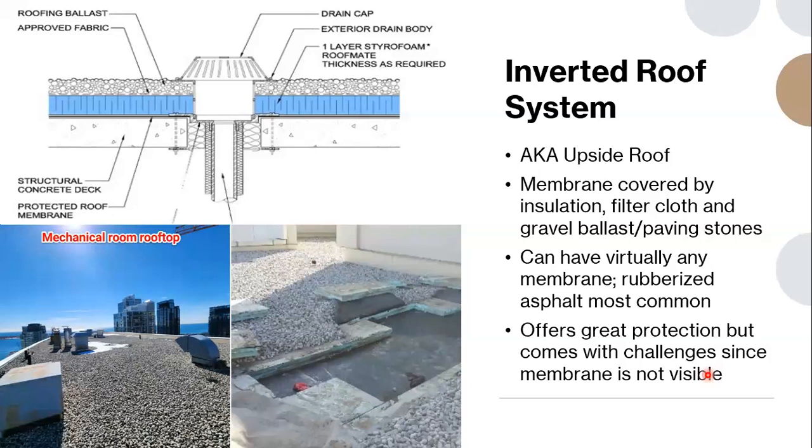So just seeing the condition of the membrane or investigating a leak and trying to trace it out, you do have to remove the various layers of the roof system like we see here. So hypothetically, if you exposed this area but there weren't any defects, or you needed to expand out further, then you just continue to open different areas of the roof system and then put that all back so that it's not left exposed to the UV rays, which can cause significant membrane damage.